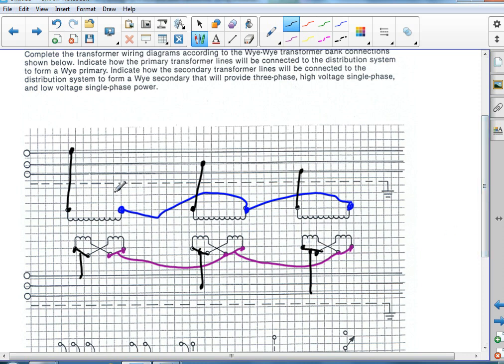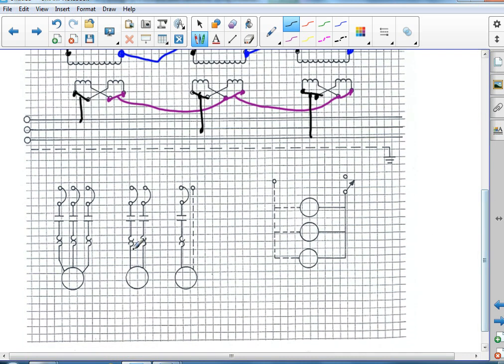Okay, so now I'm Y connected primary, I'm Y connected secondary, and now I can run my motors to phase A, phase B, phase C. I'll go A to B, C to ground, and I'll hook up control power. Or it might be the lighting panel, it's hard to say.